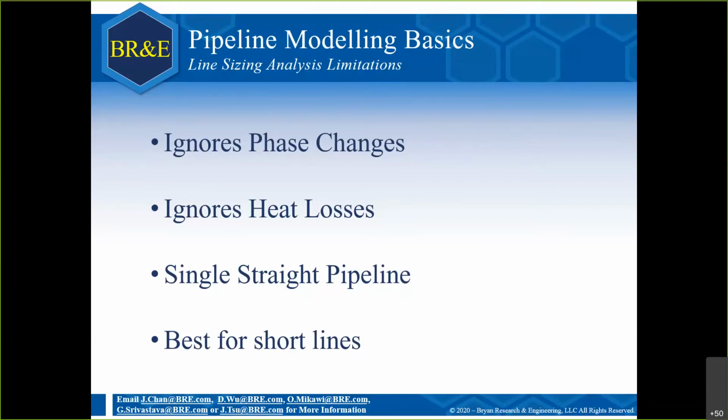So all these will not be very applicable if you're working with very long pipelines that bend and curl, or have huge pressure drops that will have huge swings in your phases. So this tool is best for shorter lines. However, even for longer pipelines, it's still useful in the sense that it can give you a good starting point.